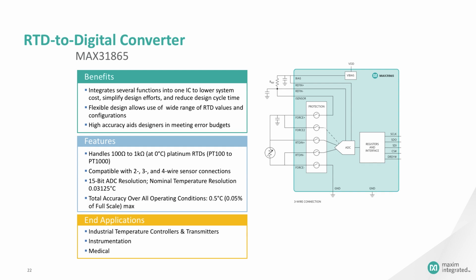It offers plus or minus 45 volts of input protection against overvoltage conditions on the RTD or cable. In addition, the MAX31865 performs checks on each of the 4 RTD terminals, so it can detect and report virtually any short or open of any of the RTD wires.